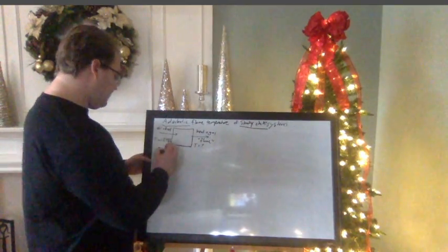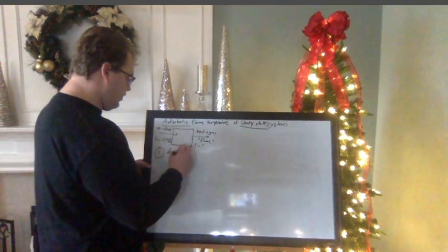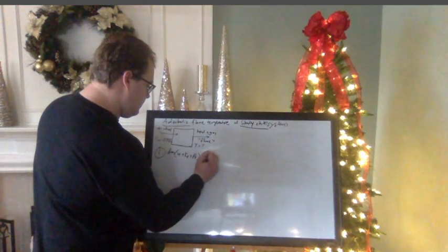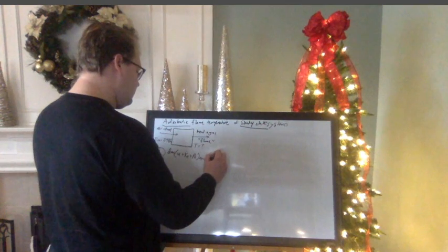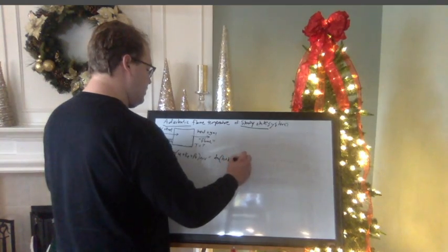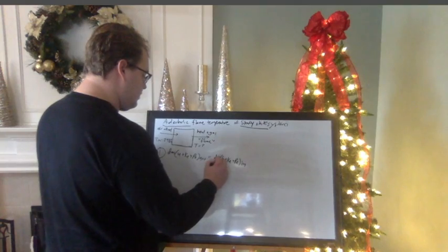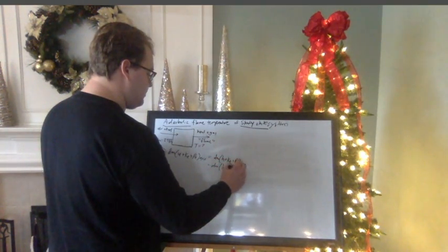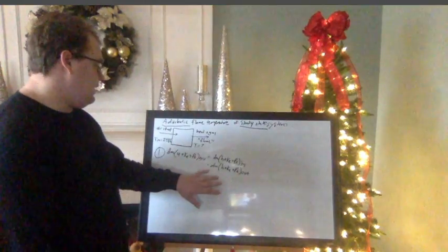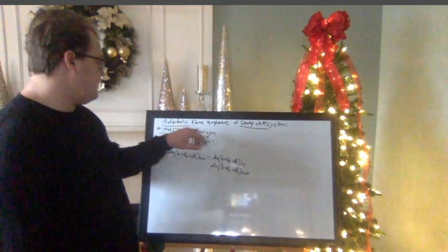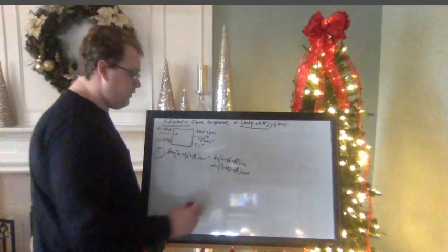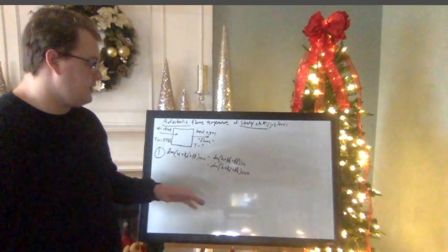So to begin, step one, I'm going to set up our energy balance. I'm going to keep this simple. Let's just say the change in mass of the internal energy plus the kinetic energy plus the potential energy of our system is going to be equal to the change in mass of H plus kinetic energy plus potential energy going into our system minus change in mass of H plus kinetic energy plus potential energy exiting or going out of our system. I'm going to ignore work non-flow for now because I just want to keep this simple. So remember, we know that it's adiabatic and it's steady state. So because of that, we can just cross out potential and kinetic energy. They're not going to form anything within our energy balance, and I'm just going to remove them for now.